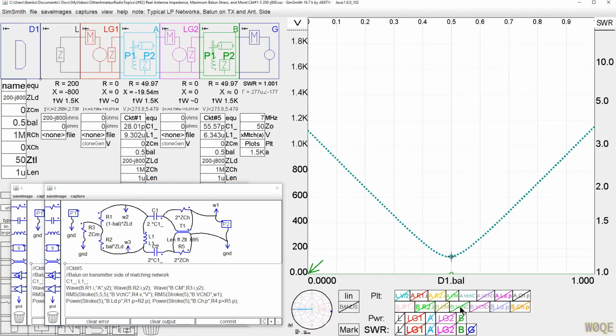And let's look at the voltage on circuit B. It's exactly the same as the A circuit. Very interesting. Both of these had a huge improvement. So we don't need nearly as big of a balun requirement if we're willing to use a symmetrical matching network.